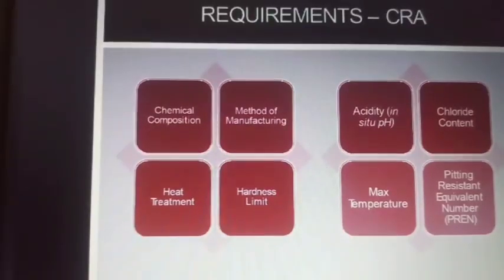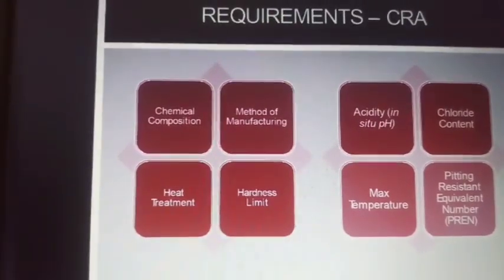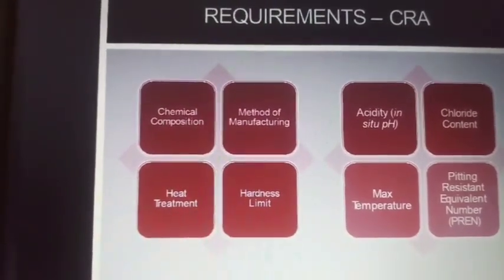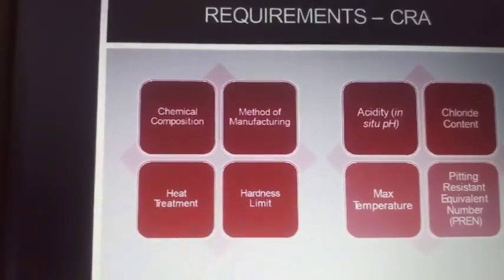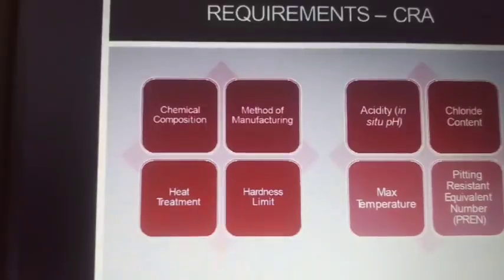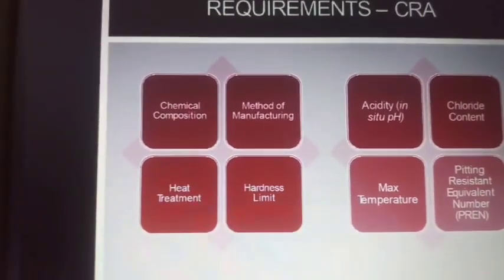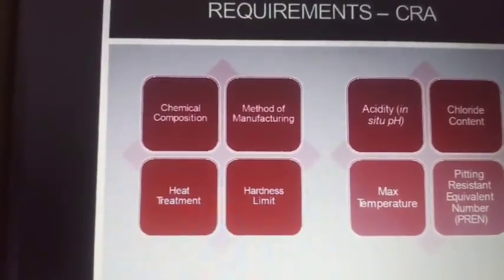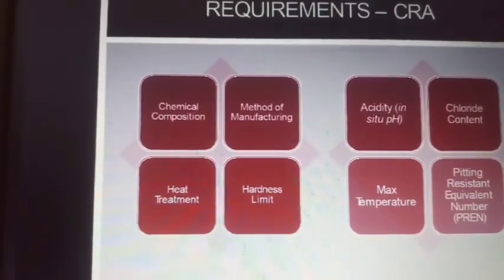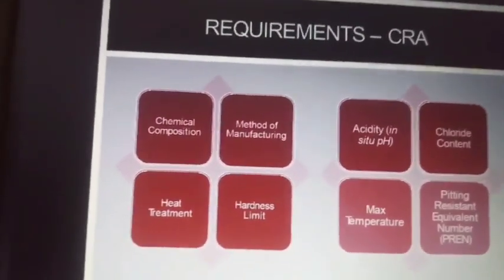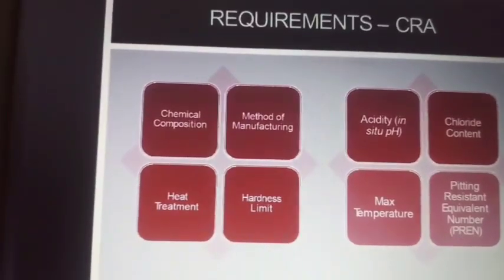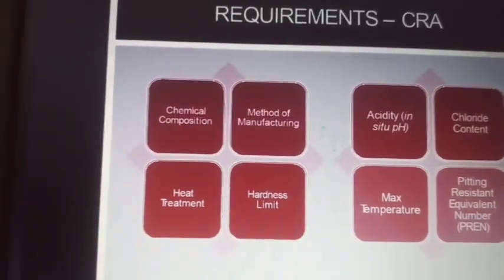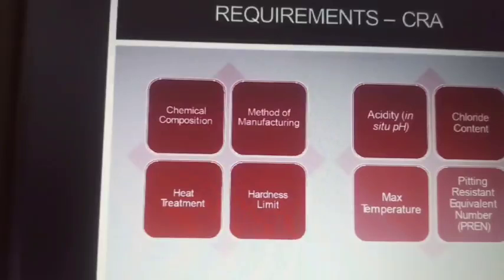The mechanism goes like this. First of all, H2S combines with water, and Fe plus H2S gives iron sulfide plus monoatomic hydrogen. Now ideally speaking, in any corrosion reaction, this monoatomic hydrogen combines with another monoatomic hydrogen and forms a hydrogen molecule, and then it will escape. H2 is a molecule and its size is too big, so it can never penetrate into the steel.